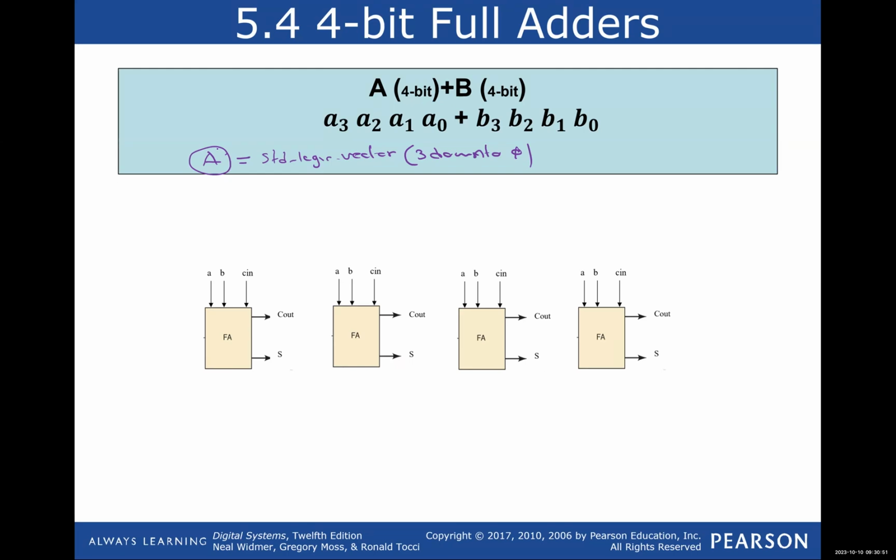So I know that for every 2 single bits, I have to have a full adder that's going to add A0 plus B0 plus what? Plus 0 for the first one. And then here it's going to be A1 plus B1 plus anything that came out from here. If the carry out here has a number, like a 1 or a 0, I'm going to load it here, and you keep going. So this is what we call a 4-bit full adder.